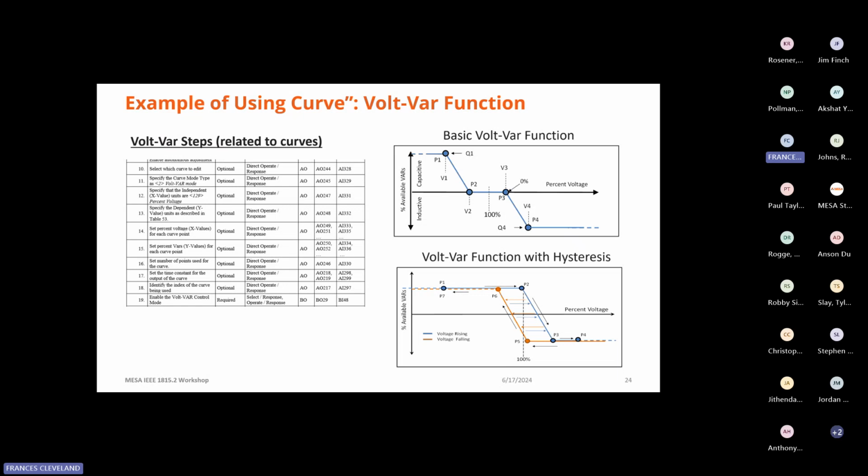Again, an example of this where the volt-var steps, I just picked up the ones that are related to the curves. I showed you these diagrams before where you have a curve associated with the function, and it could be simple or more complex. And so you select which curve to edit. You specify the curve mode, in this case, volt-var. You set the X values, you set the Y values. You can set percentages for those as well.